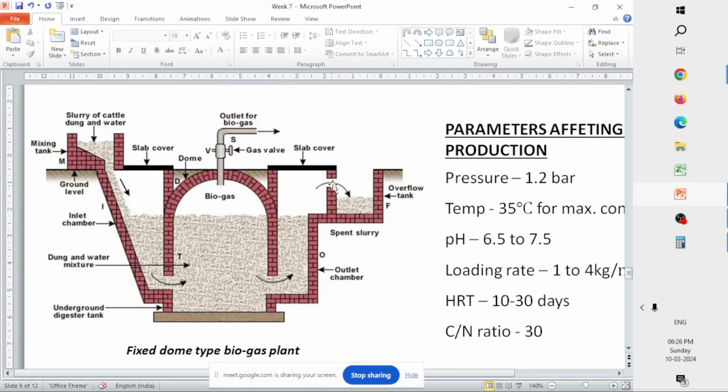Here it is fixed. You have a mixing tank, so your cattle dung or the biomass and then the water will be mixed here, and then it will be converted to a slurry. The slurry will then move towards your digestion chamber. Here your slurry will remain for approximately, depending upon the process, 30 to 60 days.